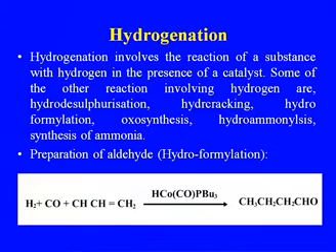Some of the other reactions involving hydrogen are hydrodesulfurization, the process which we are using in case of the petroleum refinery, and hydrocracking, again in case of the petroleum refinery. Now we are using hydrocracking along with the fluidized bed catalytic cracking for the cracking of the heavier residue which we are getting from the atmospheric column or the light gas oil from the vacuum distillation. Hydroformylation, oxosynthesis, hydrolysis and the synthesis of ammonia.